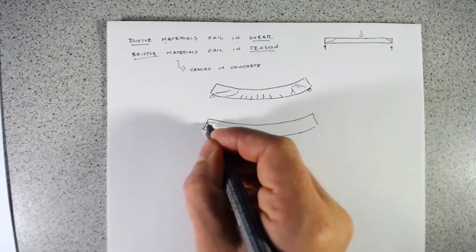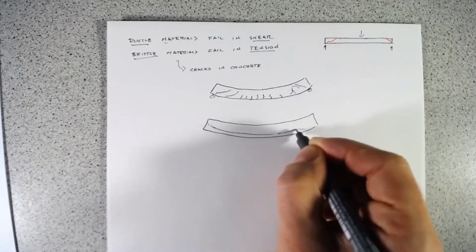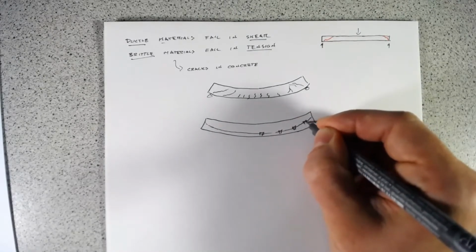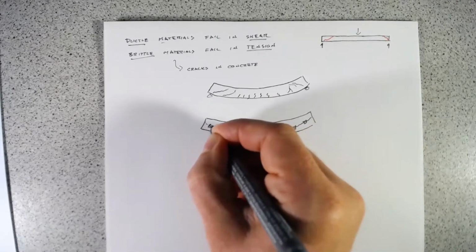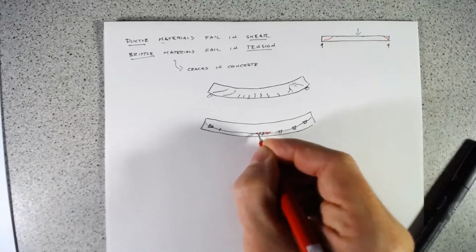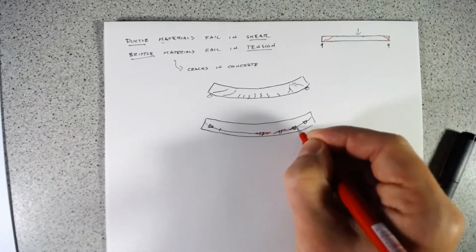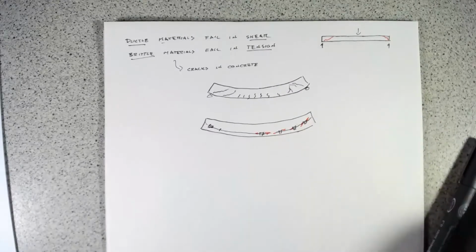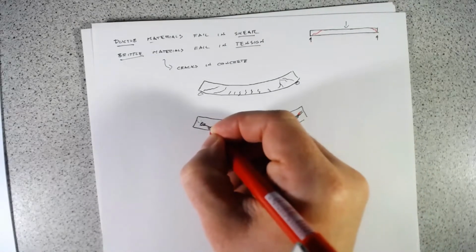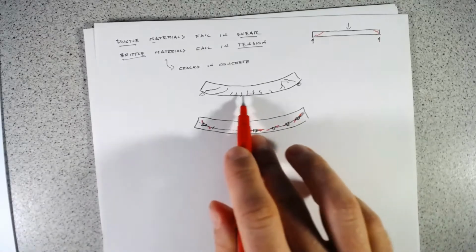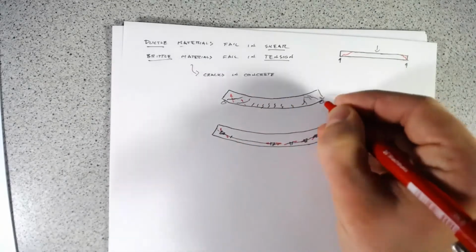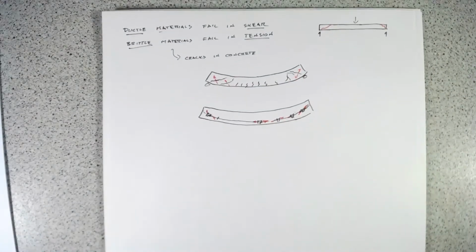So if we draw something like that, you can think, well, there's these little stress transformation blocks, and this is the direction of our main tension forces as we go through, and they get steeper and steeper as we get towards the ends, until we're more or less horizontal here, and then we're pulling in shear, or we're pulling at an incline as we get close to the supports.